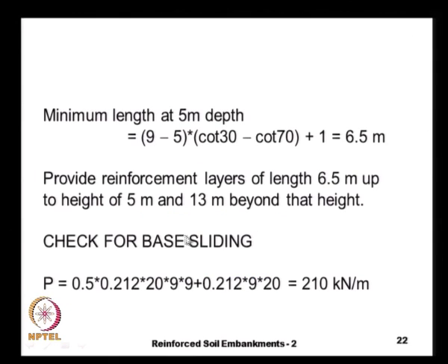So now the provided reinforcement layer length is 6.5 meters up to a height of 5 meters and 13 meters beyond that height. Let us just have a very simple design, only two lengths: 6.5 meters in the bottom portion and 13 meters at the top of the slope.